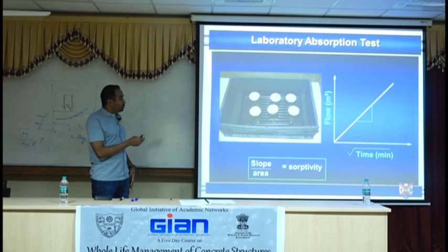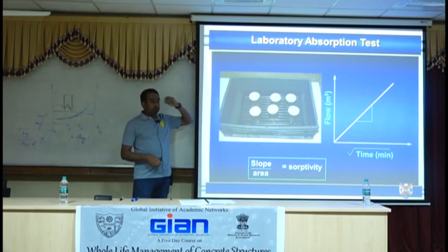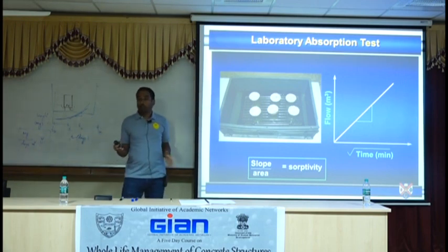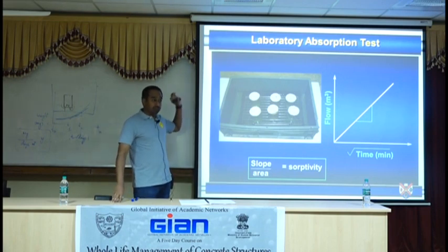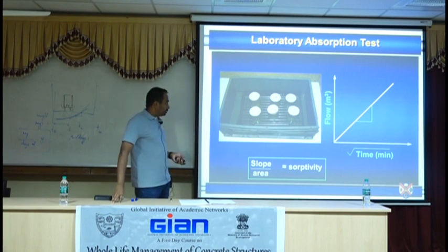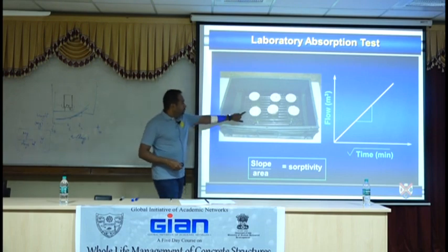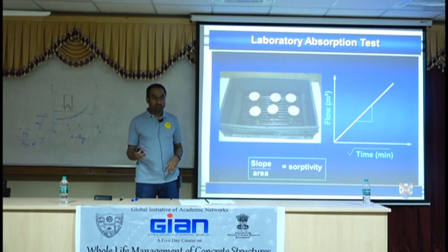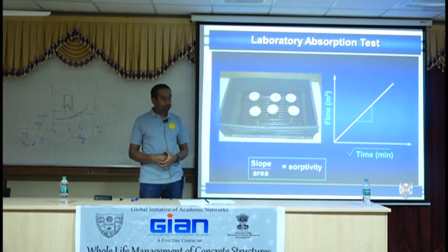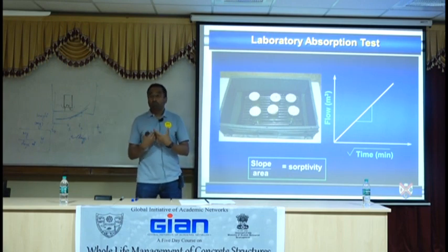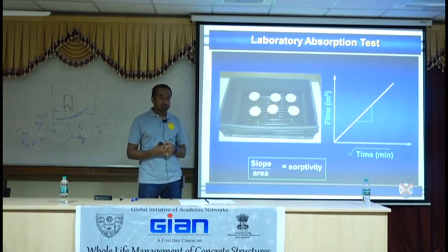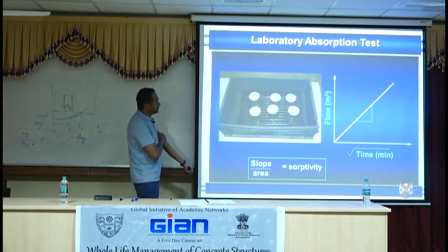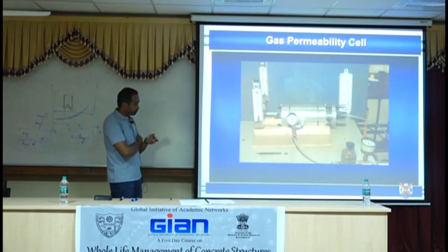Our challenge from this point, this test is standardized. It's been there for a while. So quite a lot of people use it. There's a European standard on it now. It's a very clearly defined standard. So for those who are looking to use it, can refer to the European standard. But our issue was these. That means you need to remove cores from the structure to test them. You need to dry them, you need to test them. We prefer non-destructive testing. So we wanted to evolve from that to something that you can apply on the surface.